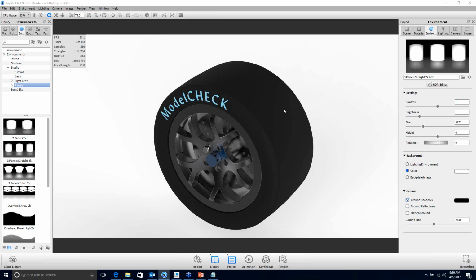So one of the questions here says, are there any issues with surface models in Keyshot rendering? And I assume that's asking about if I have a quilt from inside of Creo, so basically a non-solid 3D quilt model. Are there any issues with it inside of Keyshot rendering? No, there are no issues with it. Keyshot will treat it and visualize it just like Creo does, just like a quilt with no thickness at all to it, and you can still apply materials or colors to that quilt.